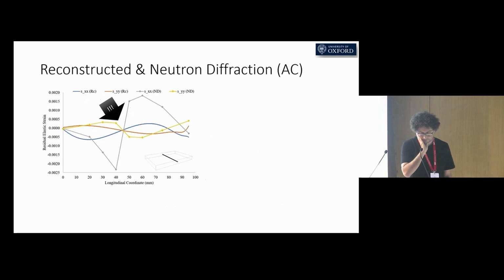Here are the results. This is a finite length weld bead. That means the weld bead travels up to a point and it terminates. It is around 50 millimeters from the cut surface. So the right side belongs to the cut face, and we penetrate inside the body. These neutron diffraction measurements are taken after cutting the plate. So these are the conditions after cutting.